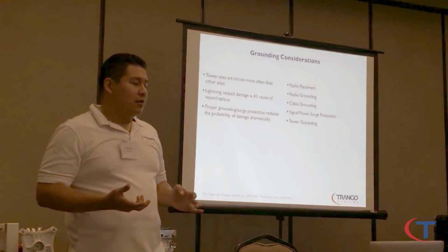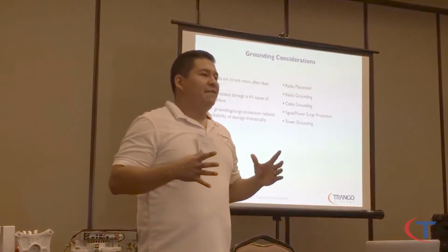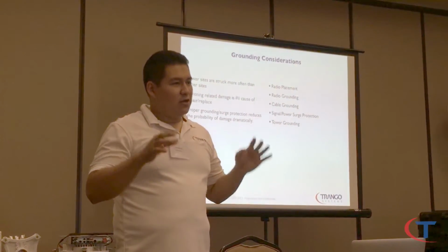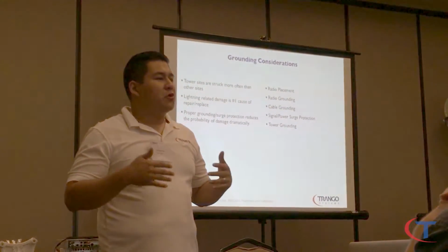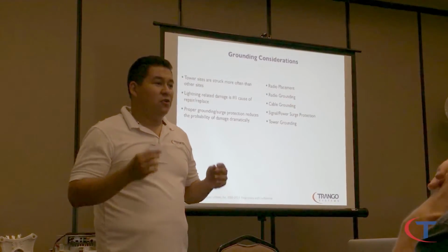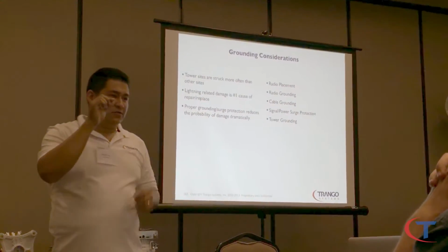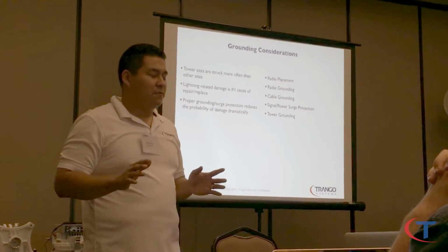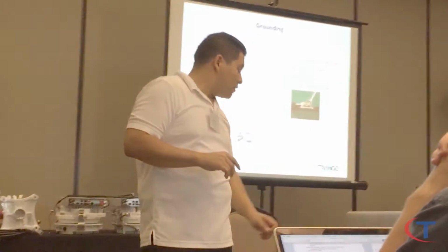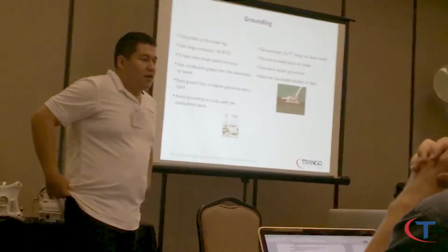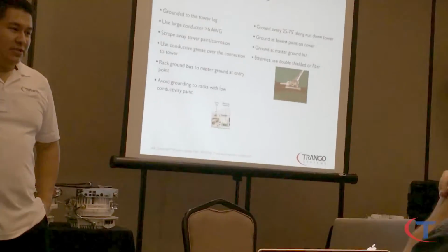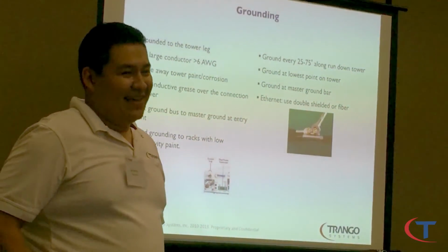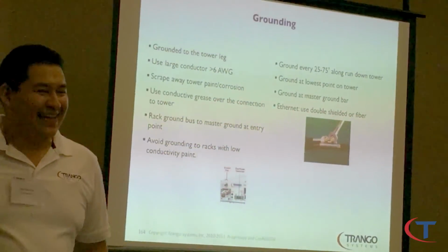Tower grounding. The tower must have a common ground. If you have a ground differential voltage on the actual site, you're going to burn IDUs really fast. There's going to be a voltage between the ground and the physical ground. And that's going to just wreak havoc on the actual IDU. Are these rebuildable? Can you replace the tube in this, or is it just toast? One-time use. After that, you're done. Goodbye. Yeah, $15. Buy them by the case.